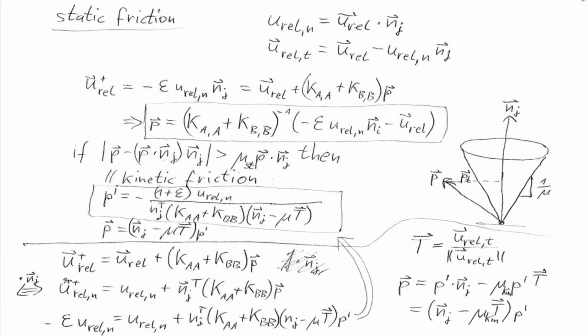And so what this does is basically it simulates the effect that when you have a rigid body and you give just a little push, it will not move usually. So that's called static friction, where the body's kind of sticking. But at some threshold, when the push is strong enough, it will start sliding. And that's called kinetic friction, because still there's an opposing force or resistance. Okay, so what do we need to change to simulate friction?